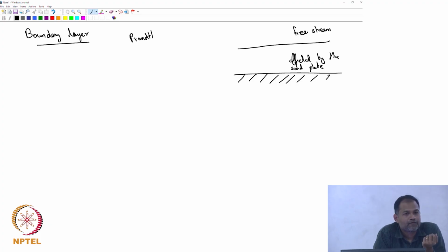Or in other words, if you talk about Bernoulli's equation, does it contain viscous effects, or do you neglect viscous effects when you derive Bernoulli's equation? You neglect them, right? So you would think that at a very high Reynolds number, I should be able to solve my fluid flow by just using Bernoulli's equation, and I can completely forget about the viscosity of the fluid. So that was the initial thought. And then there were some experiments. They looked at flow past a body. Let's talk about flow past a cylinder.